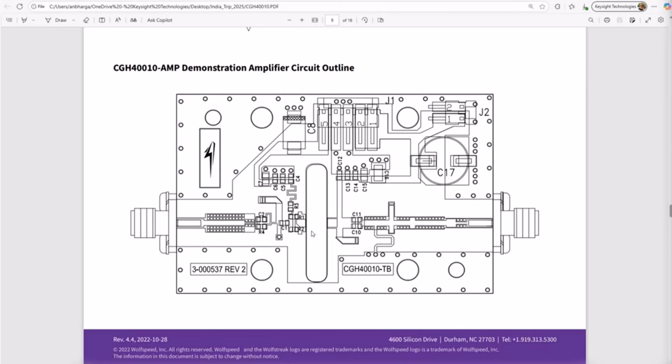As I said, these power devices are very sensitive, so you try to put as many via holes as you can. Plus, you should put these via holes as close to the ground point as possible. Wherever your component is connecting to ground, you should immediately see one or more via holes. There is nothing wrong in putting more via holes. It doesn't cause you any trouble. It actually benefits you in many ways. Okay, so those are some practical guidelines which is important to cover.